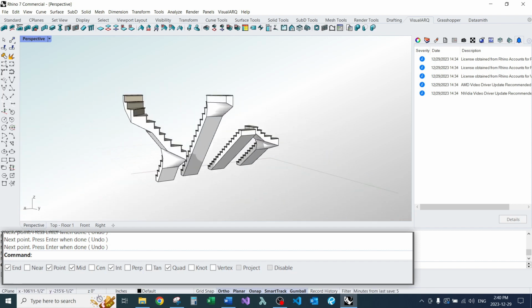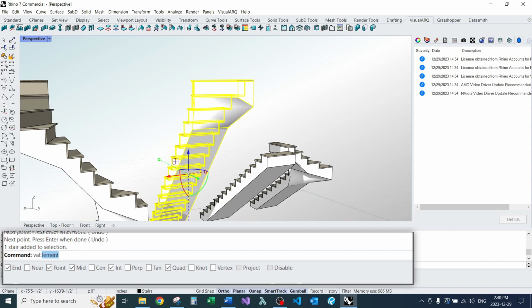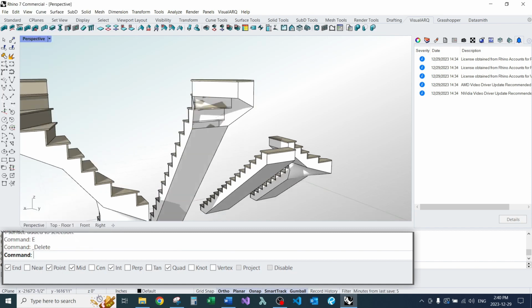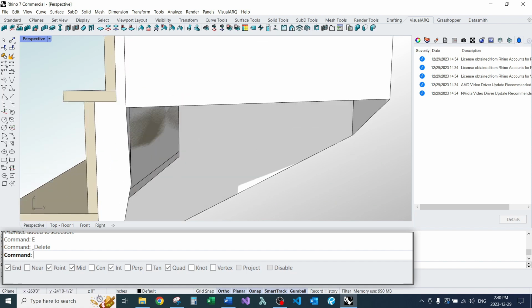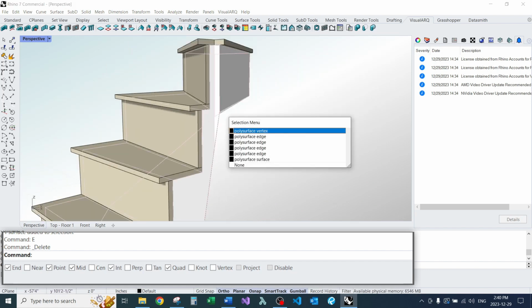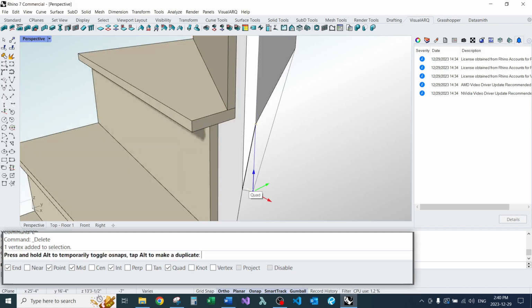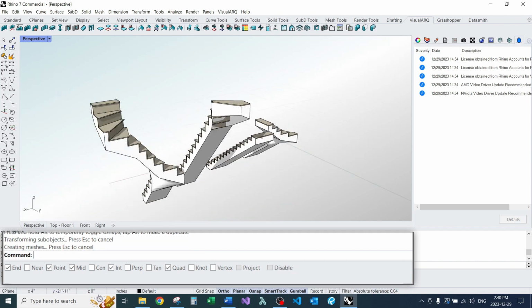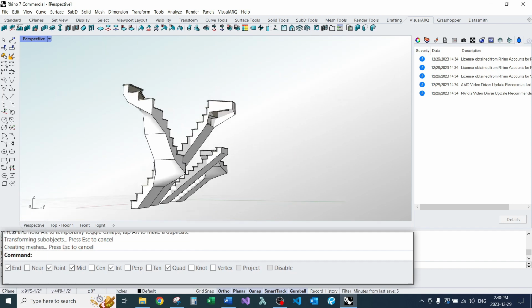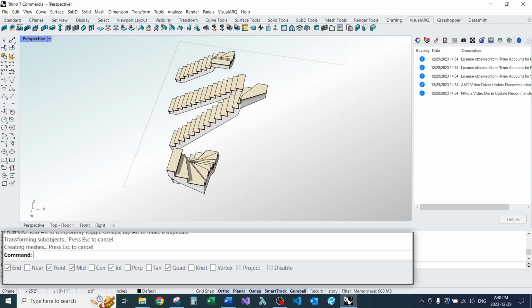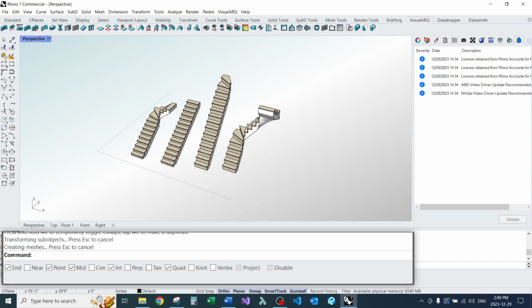If the stairs aren't quite right, you can always, I think there's a VA explode. I think I just use maybe the normal explode command. I can delete that surface, and if I really wanted, I could probably do whatever I had to do to fix the surface. So even if your geometry, whatever the supporting structure is, isn't quite right, at least you have something really good to start off with. So that's one alternative to manually modeling stairs.